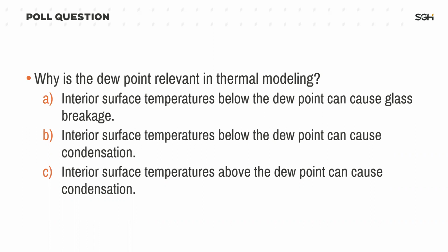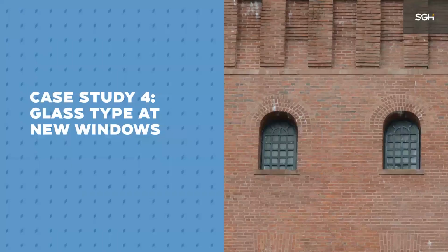I'll give us another 5 seconds or so. All right, great. Yes, it is B. They're important because interior surface temperatures below the dew point can cause condensation.